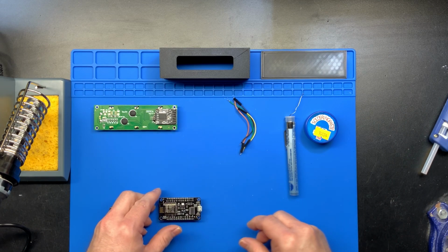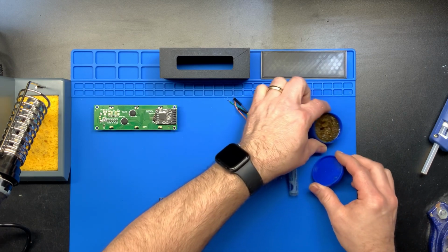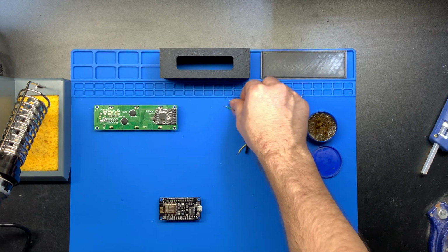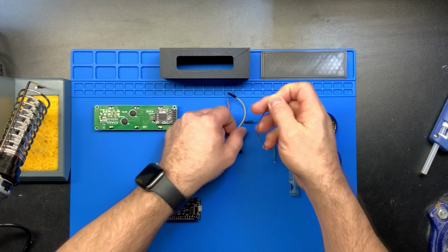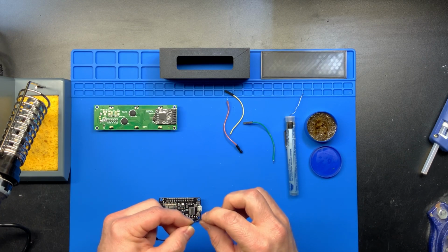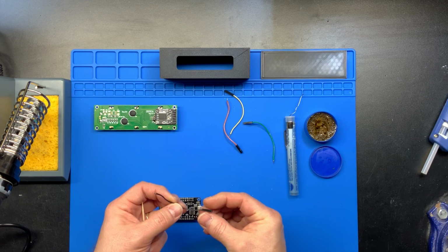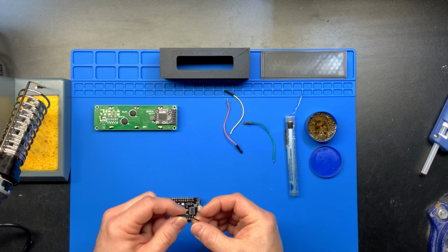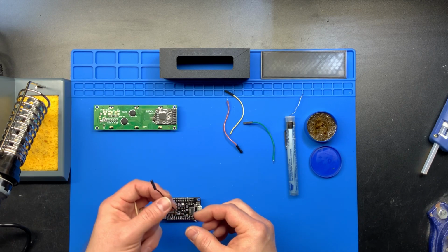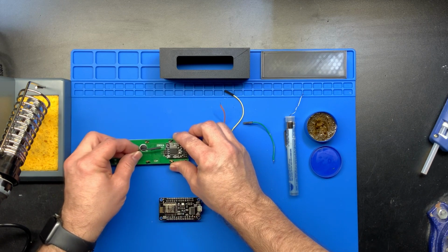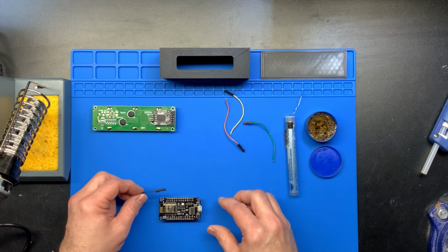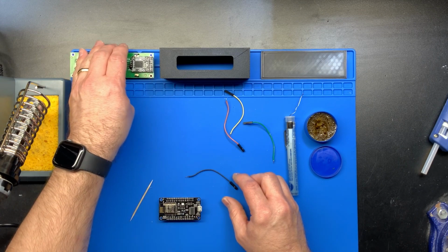So the first thing we'll need to do is get out the paste, and I'm gonna start with the ground. So I'm gonna use this black cable. Now I've already pre-soldered, added tin to the leading edge of the cable, and on the other end I've left the female connector of this jumper cable here, so that I can easily connect it to the I2C module. So we'll just move this here for now.